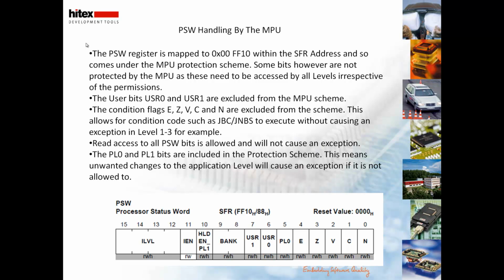Unfortunately for us, the RETI is an instruction which is also protected, because if you think about it, your operating system would normally have access to all of the interrupts, and maybe the user application code wouldn't necessarily have access to the interrupt structure.